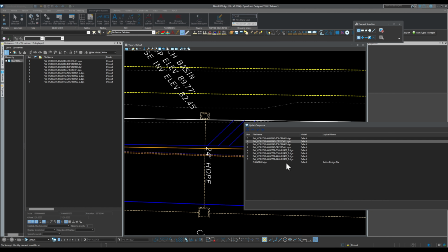Basically what I'm trying to say is when you make the plan, think of the layers and how they're going to look. So you want the focus of your plan and the top priority here to be what your plan is. Your plan is roadway. Of course, the design is going to be on top after the alignment. The alignment is going to be on top of all of them because we need the alignment. That's how the contractor uses it. It's very important in any plans. And then after that, order what you need to show.